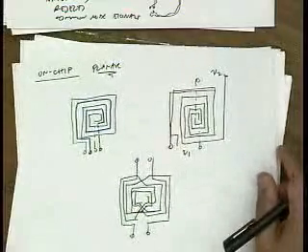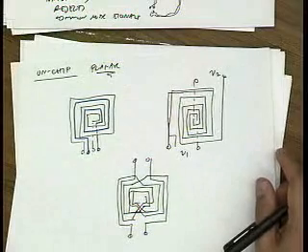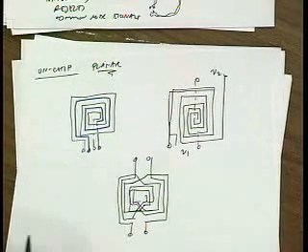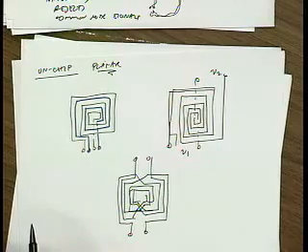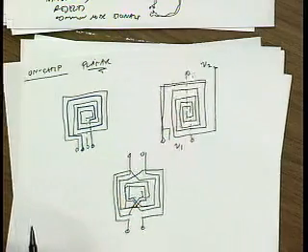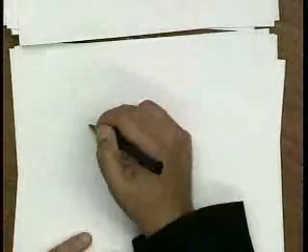Okay, any other questions? Yes? So in the twisted pair example, and even here, how do you make a transformer with turns ratio not equal to 1:1? That's a good point. Generally, it's harder to do that. You can't do very large ratios. What you do is you put turns in parallel. So let me show you how you would do that on chip, and then you'll get an idea.